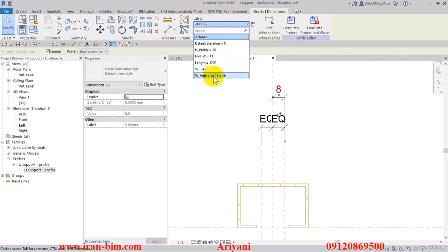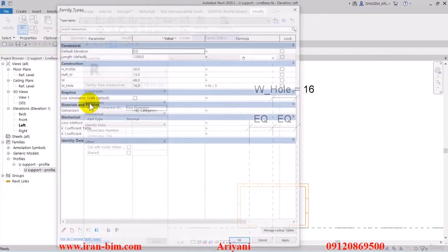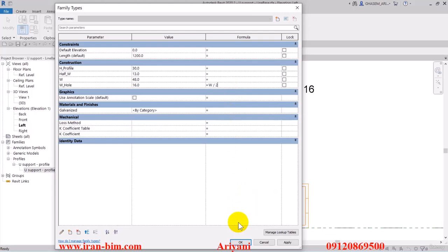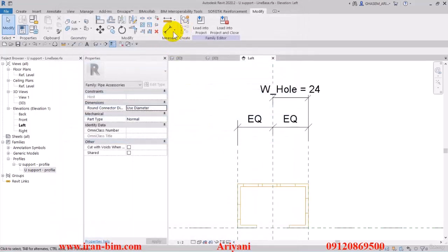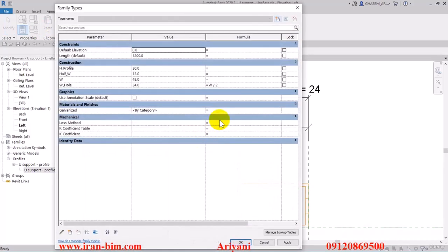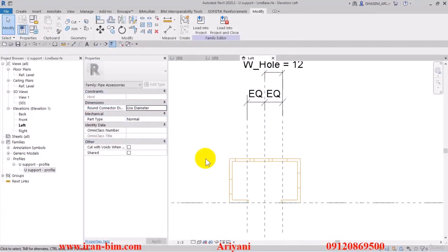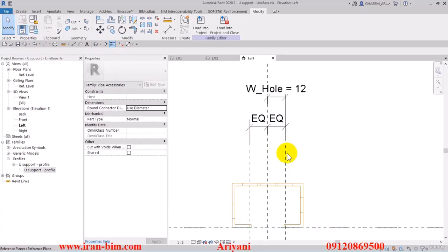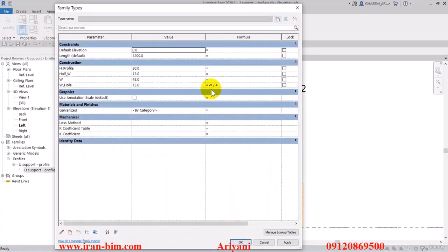And from here, we can do one side first. All right, so load up the formula and there we go. And then after that, we can go over to the family types and put this on divided by 2. Let me just change it to 4 and all right. Now using the align tool, I'll lock this line with this part and this line with here, and the one in the middle is locked as well. Now I'll go over to the formula section and put these in parentheses so we can get it a bit neater and add in 2 millimeters.